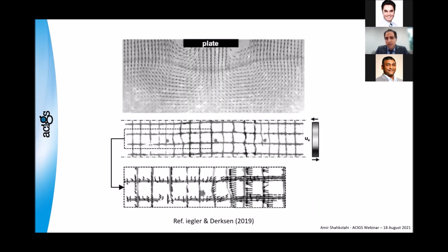I like this photo very well. It's from a study in 2019. As you can see, the darker area is the base course and the lighter area is the subgrade, and in between it was a geogrid. So this shows the direction of the strain and forces in the subgrade. And also you can see in the geogrid, these flashes are showing the forces in the geogrid. So it clearly shows what's happening, and it's a very good example of studying these conditions.